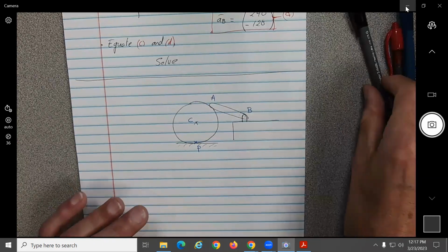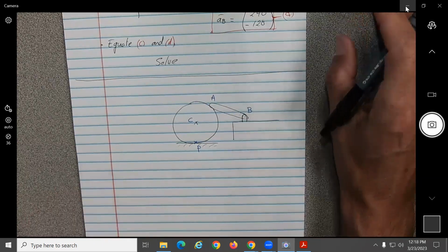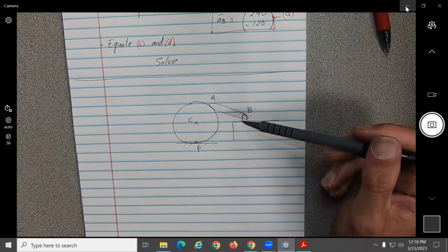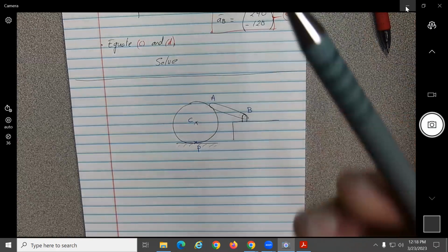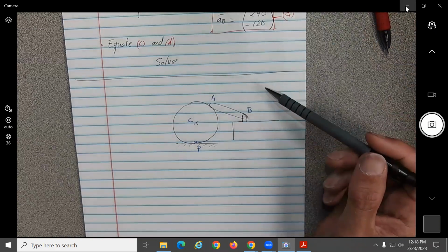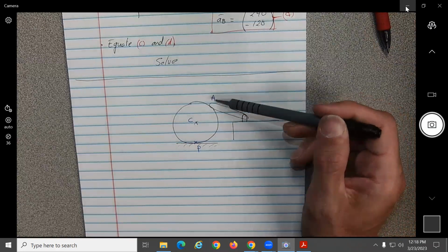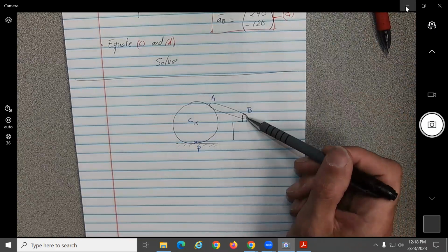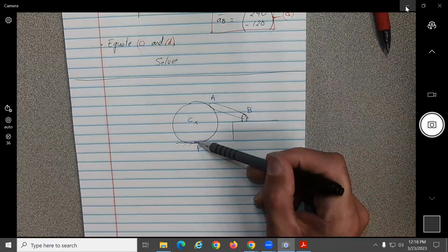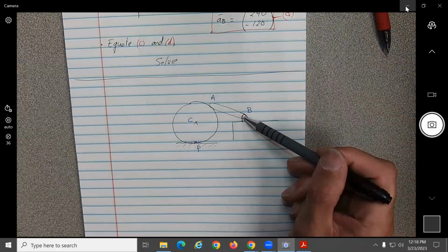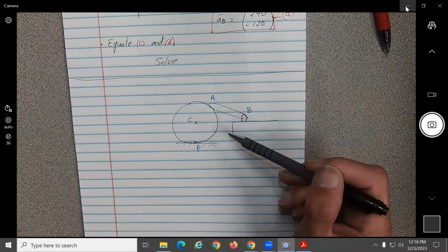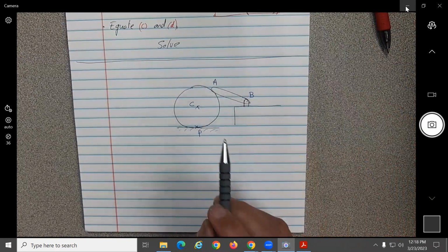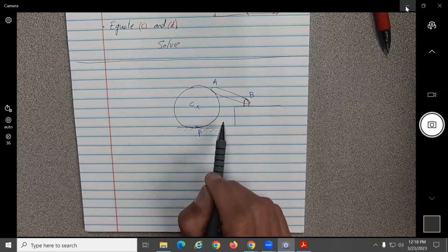Okay, so this one. Again, if you have to solve this one, I'm just going to talk about it, okay? So like always, the strategy is to find the velocity or the acceleration of one point from two different locations. Over here, obviously, is always the point of contact. So we can find the velocity of A from which two locations? B and C. From point B, and let's say point P. So do we have a relative term between B and A? No. Are we going to have a relative term between A and P? Yep. Yes.